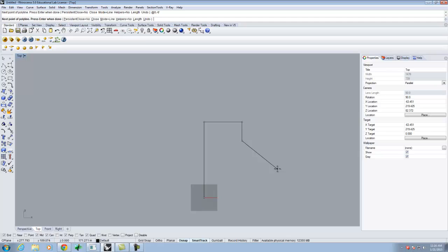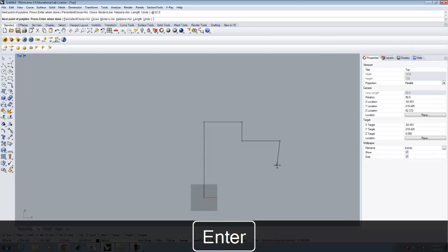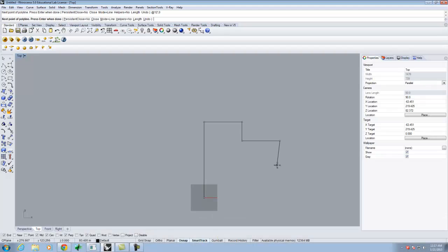So we can continue in the same vein with relative coordinates, right? Use the @ sign, and we're going to go over 12 feet now. So it's 12 in the x direction, 12 feet, 0. And we've gone in that direction. Now we would go down, so it's at 0, sorry, I'm trying to follow along and make sure that I do it in the same order, right?